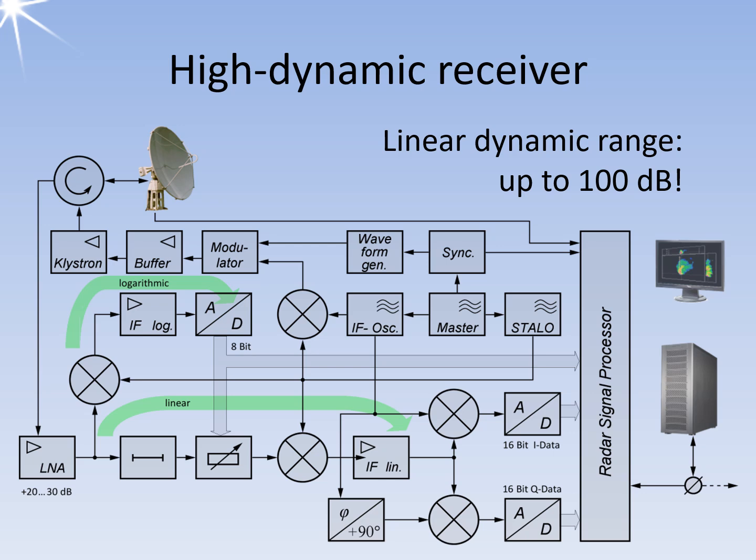High-end radar receivers designed for measurement purposes utilize a logarithmic amplifier to assess the approximate amplitude range of the echo signal. This information is then used to control a separate linear receiving path through an attenuator. To account for the internal delay introduced by the logarithmic intermediate frequency amplifier and the analog to digital converter, a delay line is implemented. Thanks to extremely fast analog to digital converters that operate at clock rates in the nanosecond range, this delay line can consist of just a few meters of coaxial cable.